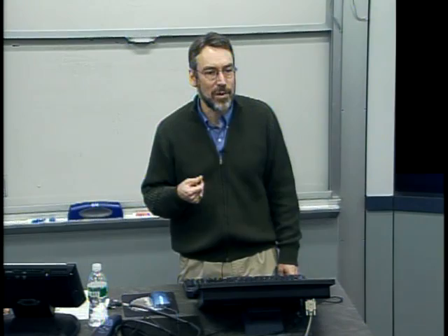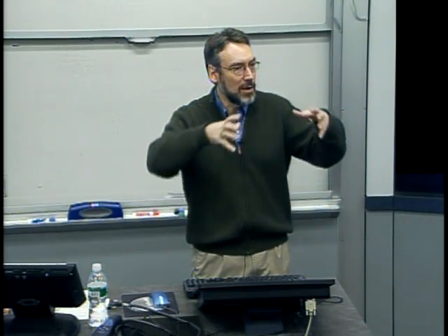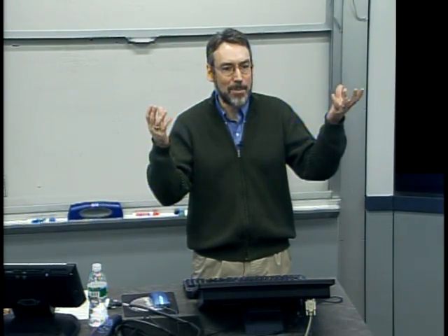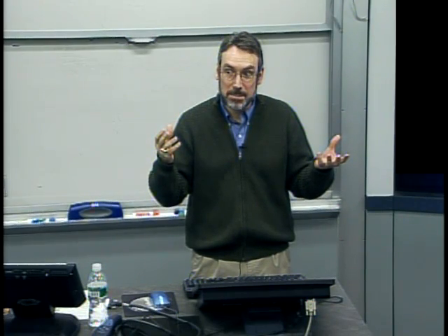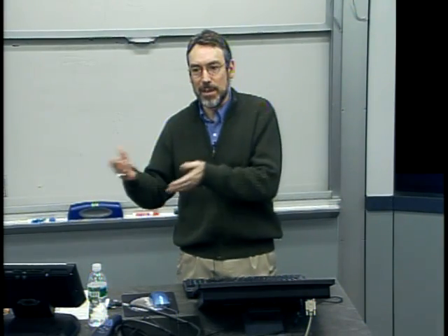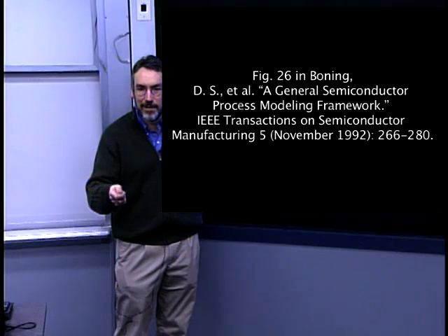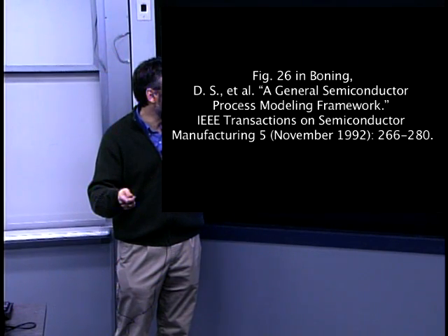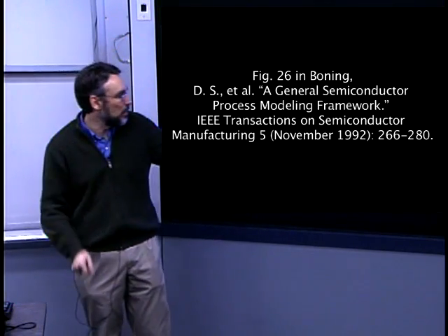So for example, every one of those coating processes occurs in some kind of a chamber. I coat up a film, I coat aluminum on the surface of the wafer. What do you think happens to the rest of the chamber? It gets coated too. So over time, you will often get buildup of material in the rest of the equipment, and there will need to be other steps to go in and clean or reset the equipment state. So actually, we are often worried not only about the product and what's happening with the product, but in manufacturing control, we're also very worried about what's happening with the equipment.